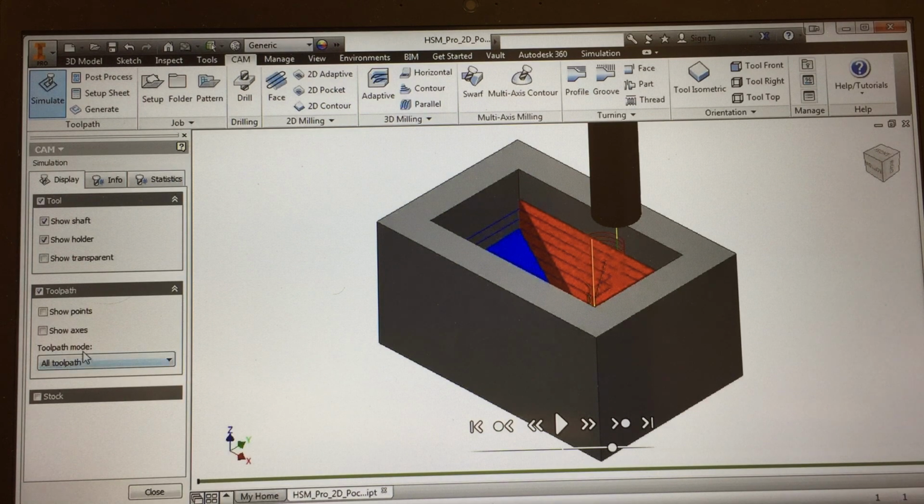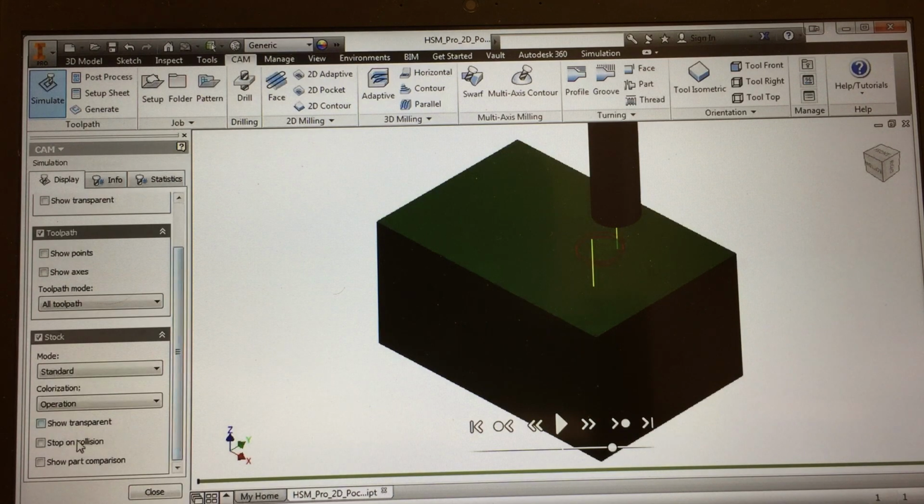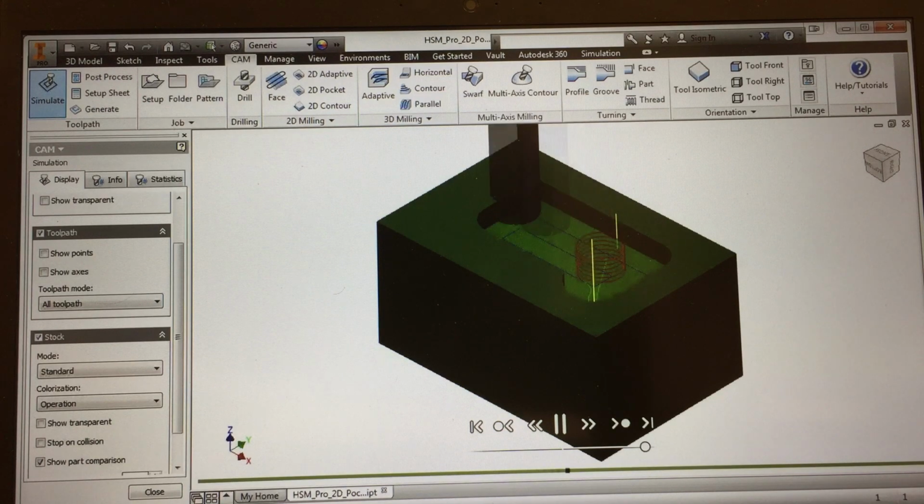The tool removes material at the depth of each step-down value down to the bottom of the shallowest pocket. The deeper pocket and corners are highlighted. Removing materials in the corners will be addressed in a later presentation. Next, the deeper pocket will be machined.